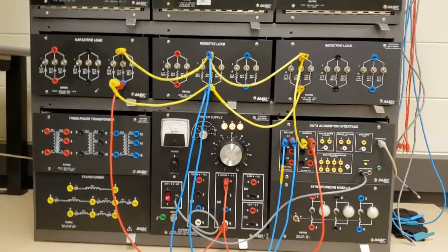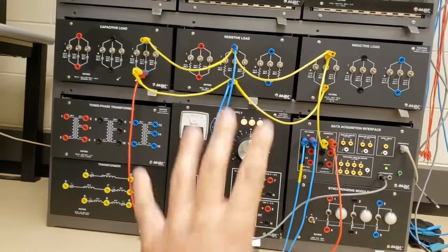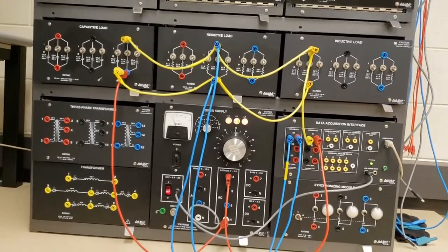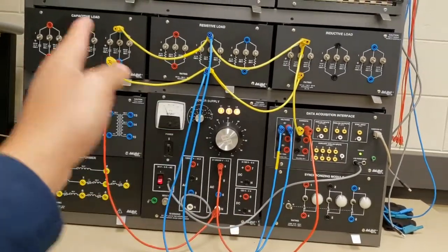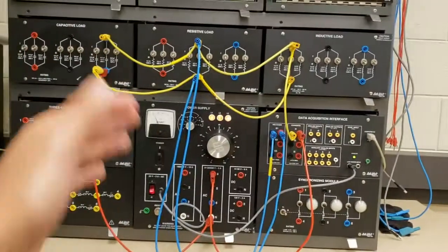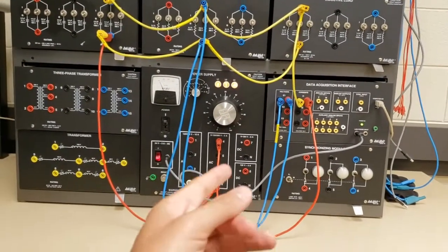All right, guys, so this is the first part of the lab, part A. I'm not going to go through all the connections because that's impossible to explain and nobody would follow me. So all it is, I'm supplying three loads in parallel. We have the resistor, inductor, and a capacitor in parallel. Each one is 300 ohms, being supplied by 60 volts.